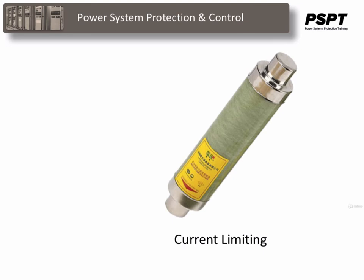The quartz fuse consists of a glass or ceramic holder, and the fuse link consists of one or more fuse wires wrapped around a heat-resisting core and surrounded by quartz granules. The fuse wires melt on the rising current wave, and silver vapor is expelled into the surrounding quartz granules and condensed back into microscopic globules of silver. The arc current continues to flow between the globules, heating and melting the quartz, which forms a non-conducting solid.